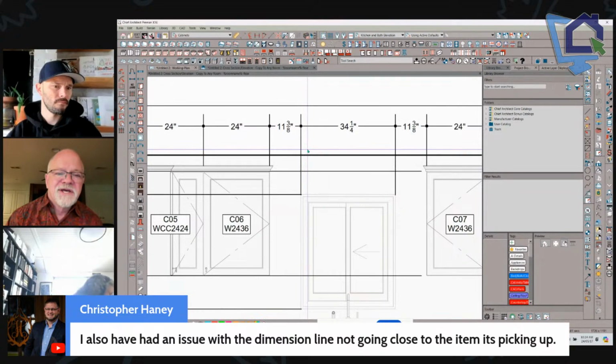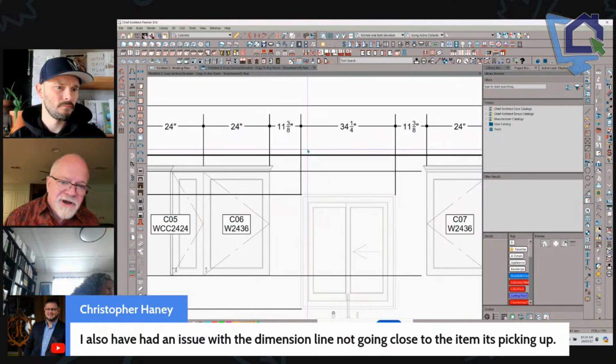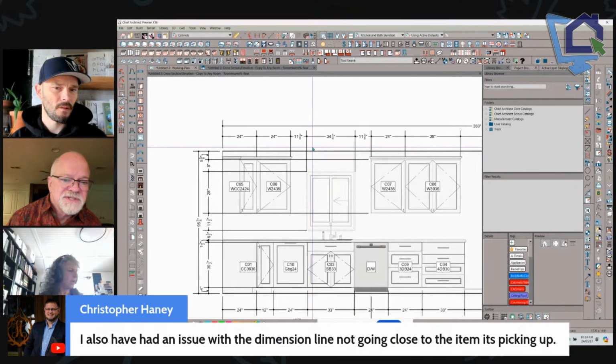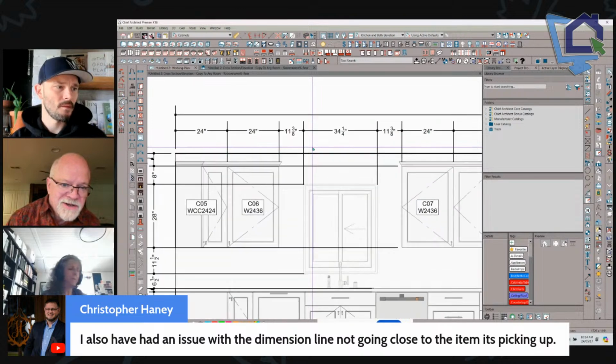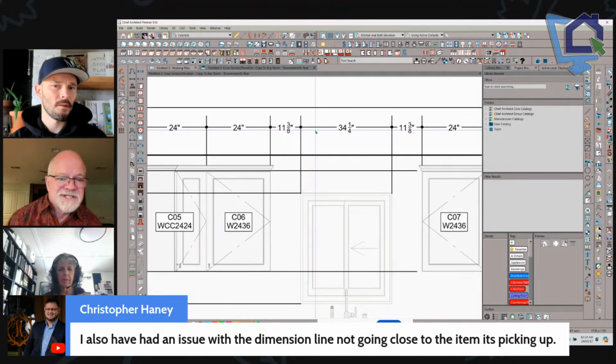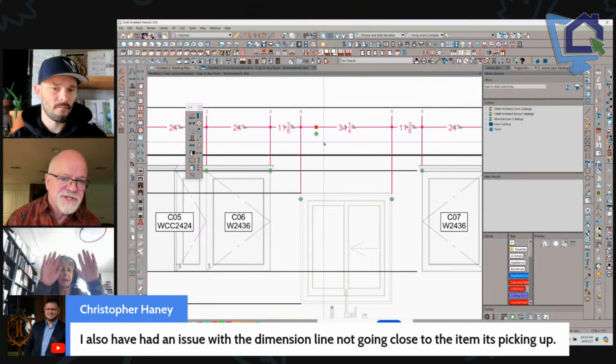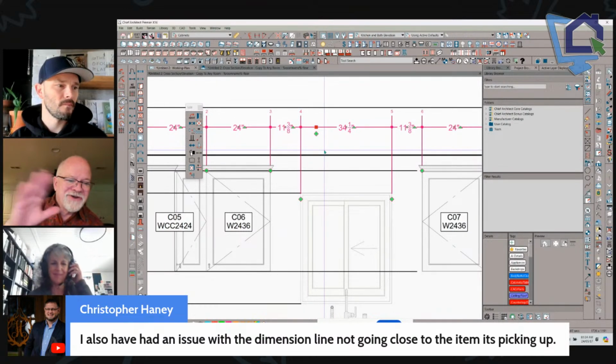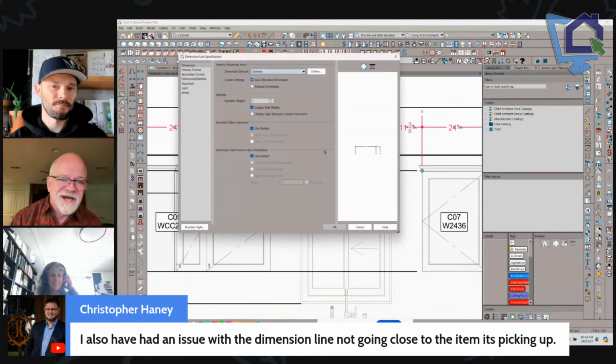You've got the object itself, the drawing, then you've got the dimension line, which he has set his default to 10 inches for his first one. So the distance between that and the first dimension line is 10 inches. He's got his extension going past there by another 4, but the separation between the two dimension lines is 7. So it works for him.